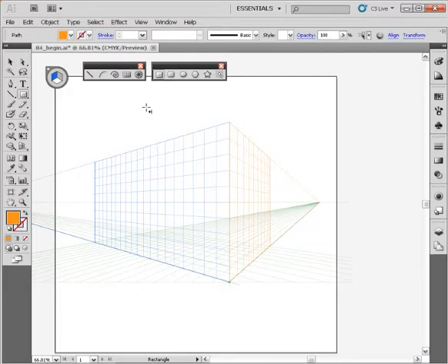You see here there is sort of a little tip here in the bottom right corner of our cursor, and it looks like a little vertical line with an arrow pointing to the left. That is a little visual indicator for you that, hey, you have the left grid plane selected as your active grid plane. Now, that tip is going to be there for any of these tools that you select that you want to draw with. Now, if we come over here and select a different grid plane here, that little tip is going to change. See, we now have an arrow pointing to the right. So if we select the horizontal grid plane, we have an arrow pointing down. So that's just a really nice little visual indicator there when you're drawing right into perspective as to what plane you have selected as the active plane.